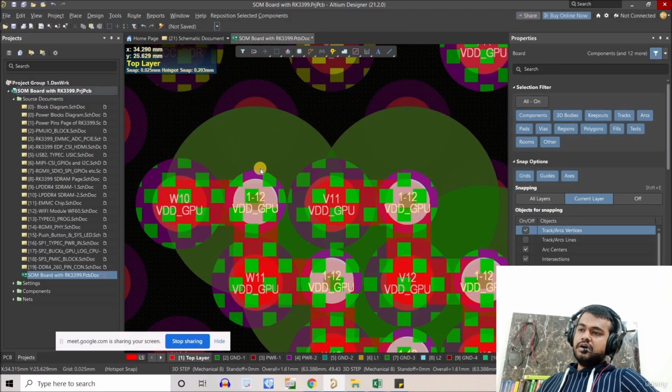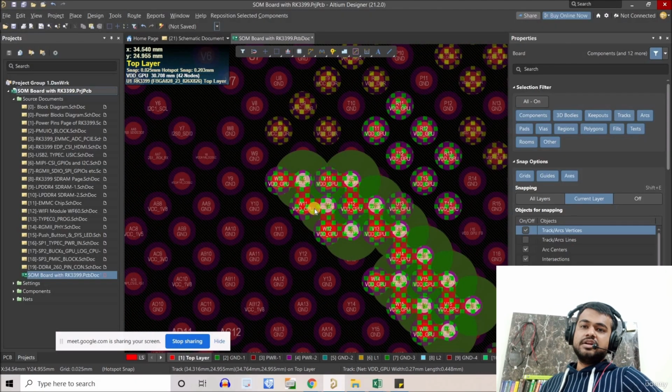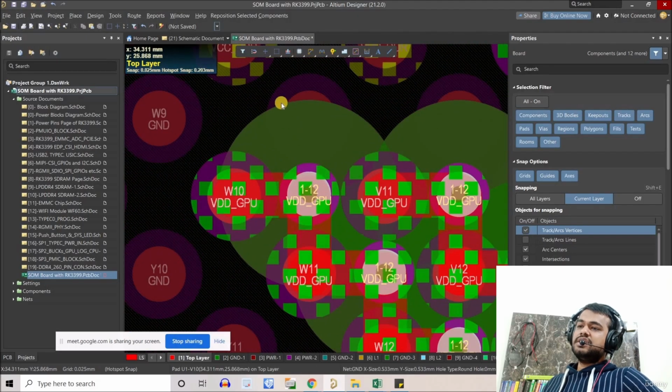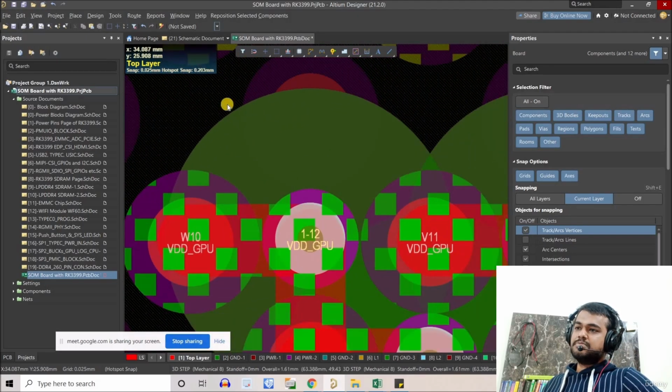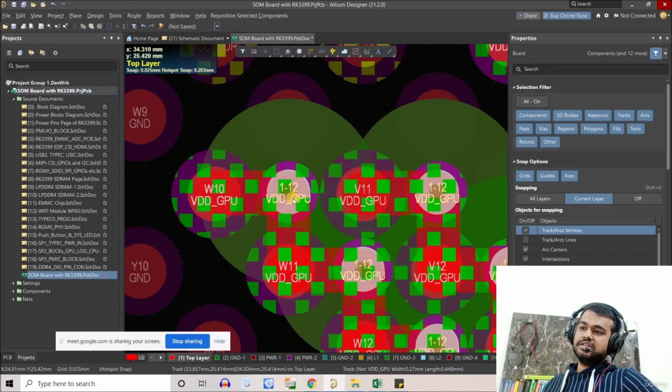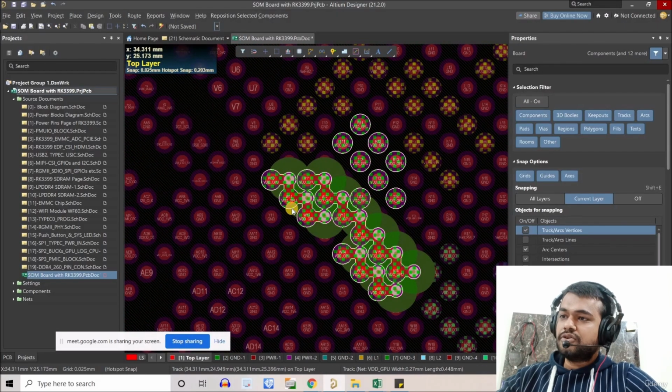So there is a term that we generally use, the through hole vias and the internal planes. So here, we are using a 12 layer stack up. We have some internal power planes or grounds that we're going to connect. So here you can see this dark green part, that is the clearance between the plane, the copper and the via, and this is huge, right? And if you visualize that in 3D mode,